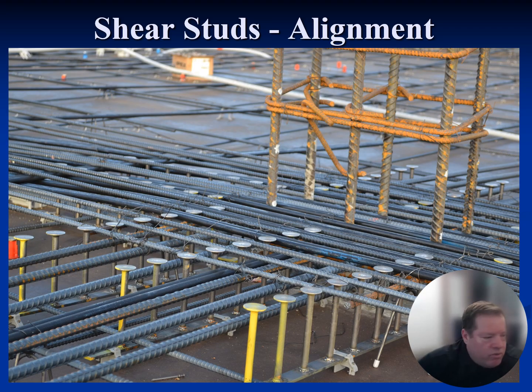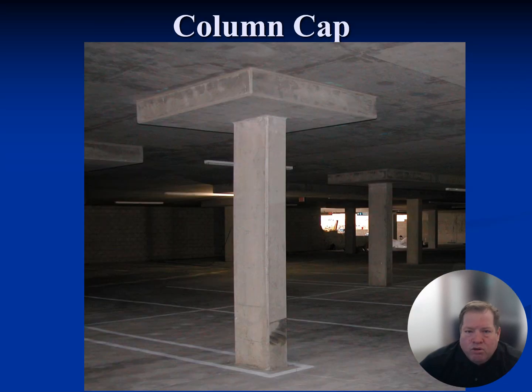The other nice thing about stud rails is that when you're doing structural observations, the rail should be the same cover as the rebar, as the same cover as the PT at the face of column. So when you look at the face of column, all 3 of those things should be in the exact same plane. If you are at a typical interior column and those 3 are not in the same plane, something is off. You don't need calipers or a tape measure. If those things are jumping or there's gaps between them, right off the bat, you can know something's wrong. So the stud rails themselves, since they are a manufactured product, they should be extremely accurate based on the slab thickness. That'll tell you at the column if the PT and rebar is located correctly.